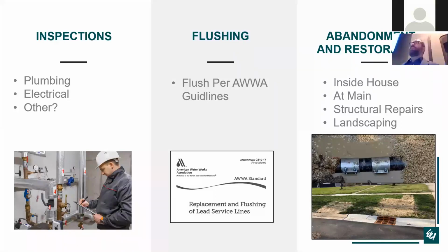Another important item to take care of before the service is handed back over to the resident is to make sure it's flushed per AWWA guidelines. Since we are going to be doing work on the water service, any lead that's existing is potential to be shaken loose and enter their lines. So flushing is pretty important.